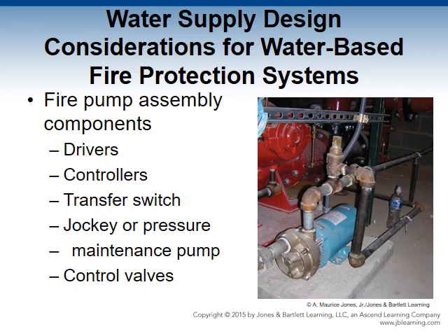Control valve must be an indicating type valve. It must be supervised by one of the methods listed in NFPA 20, such as electronic monitoring, lock, or sealing the valve or limiting access in conjunction with weekly inspections. They are typically installed on the suction and discharge side of the fire and jockey pumps. All should be kept in the open position.